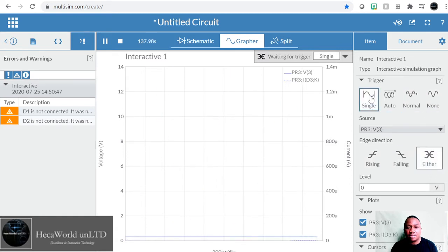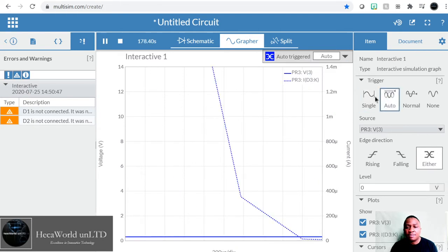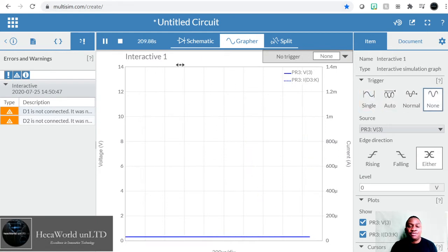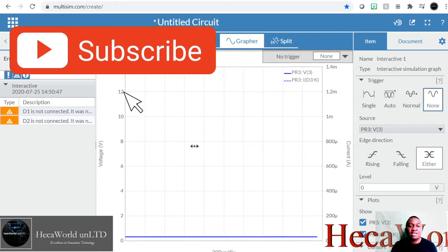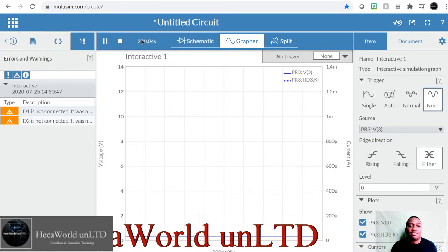Freeze on single. Alright, you can see the falling edge and then the rising edge on the other side. Let's make it full wave so we can understand this properly. Sometimes you see the rising edge because it has to charge up the capacitor and then discharge. So we're losing half of the voltage.